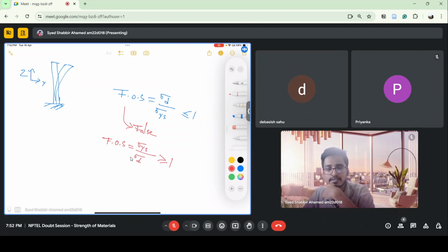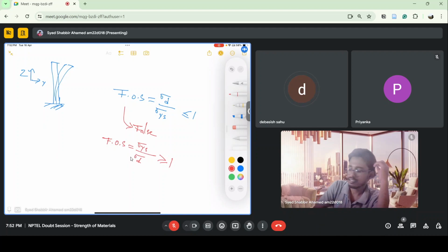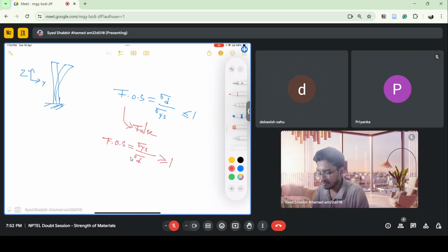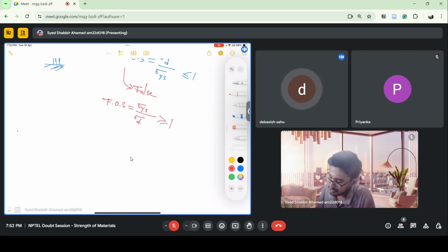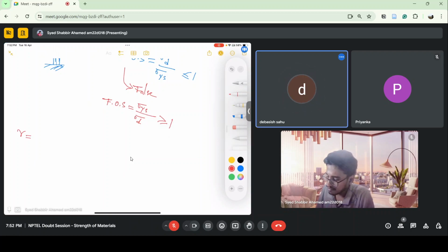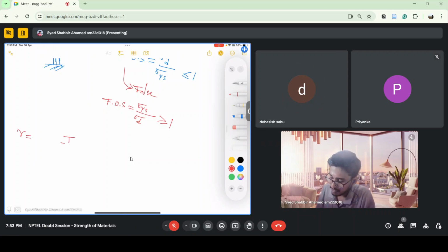Radius of gyration is nothing, you can say it is one imaginary quantity. Let's see, moment of inertia. Whenever we take moment of inertia, we calculate something, and area moment of inertia is generally defined as the area of the cross section times the radius of gyration squared.